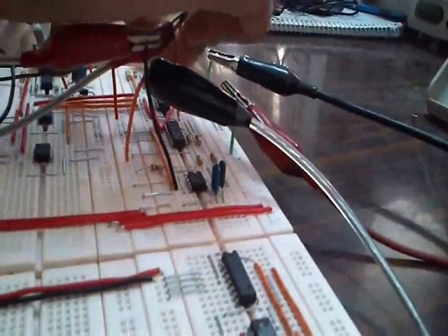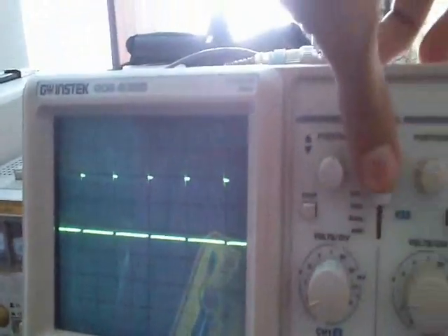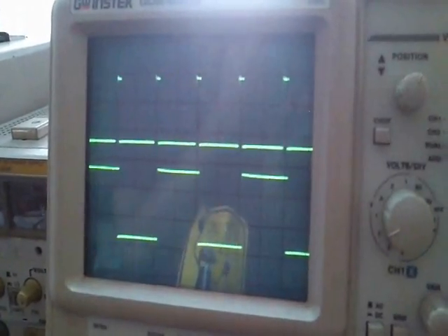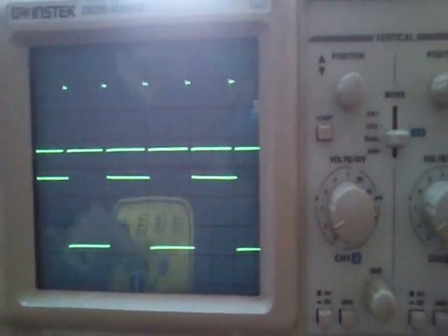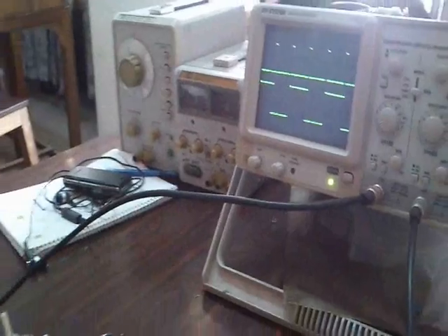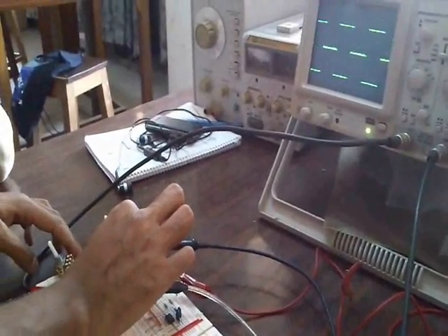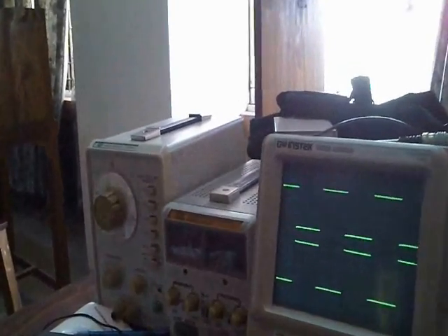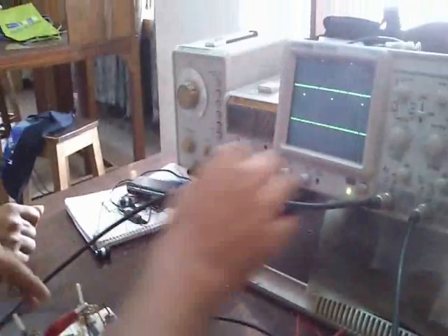This is the main clock of our system. We generate it with a 555 timer. Now this is the output of our T flip-flop. This T flip-flop is needed for producing the shifted clock. We'll see later. Here we see the Q and Q bar of the T flip-flop output. Here it is. Now our shifted clock is generated.